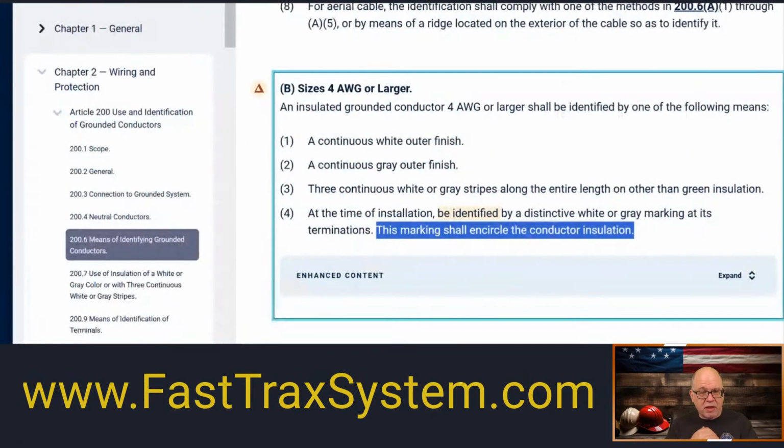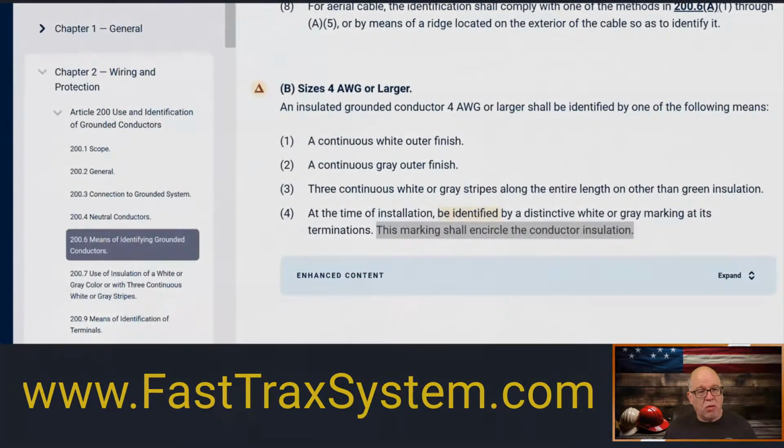What I want to tell you about those is that the only reason somebody would use one of those is if they don't want to pound rods, because that's the only requirement for ground resistance: for rods, pipe, or plates. With two rods, if you can't prove that it's 25 ohms or less, then you install two, and if you can prove it, you can drop down to one. It's much cheaper to buy the 6-gauge copper wire and the ground rod and just have the helper pound it.